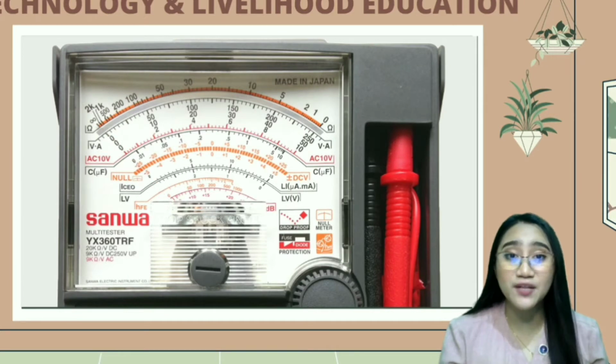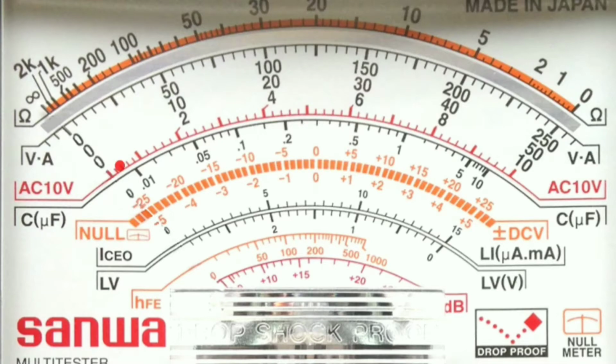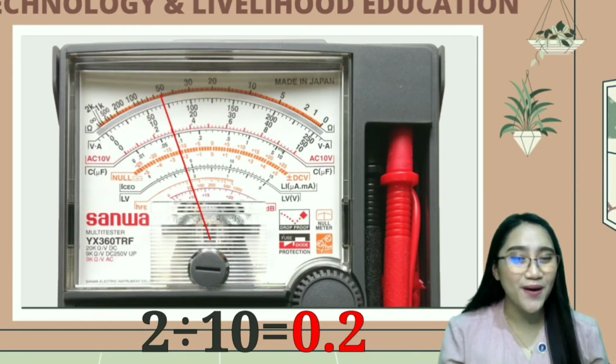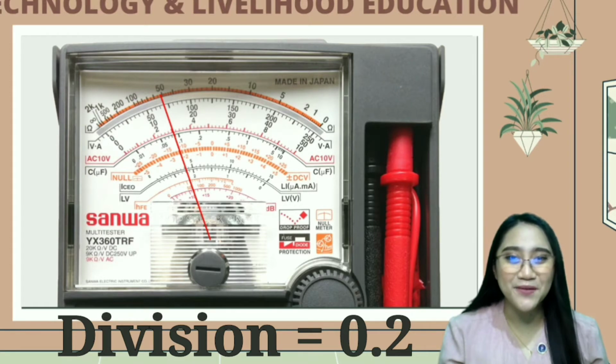What if the needle points here? What are we going to do? First, we must know the values of each division at the range of 10. How many divisions are there at 2? Let's count. 1, 2, 3, 4, 5, 6, 7, 8, 9, 10. There are 10 divisions at 2. So 2 divided by 10 is equal to 0.2. Meaning every division is equivalent to 0.2.